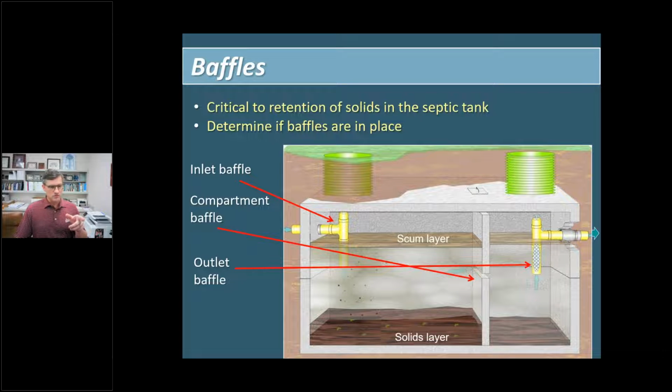One thing I would say here, just from my experience with some installs on these, is try as best as possible when inserting those pipes. There's usually a boot or a bushing in each of those access points. In a perfect world, you're cutting out your access hole to exactly fit that boot, so that boot has no wiggle room. It is as watertight as possible, and then, of course, you put your pipe in there. But sometimes I've seen that hole get cut out a little too big. The boot's in there, but it's not a solid fit, and you could get some leaking from that. So that's just a minor thing to think about.